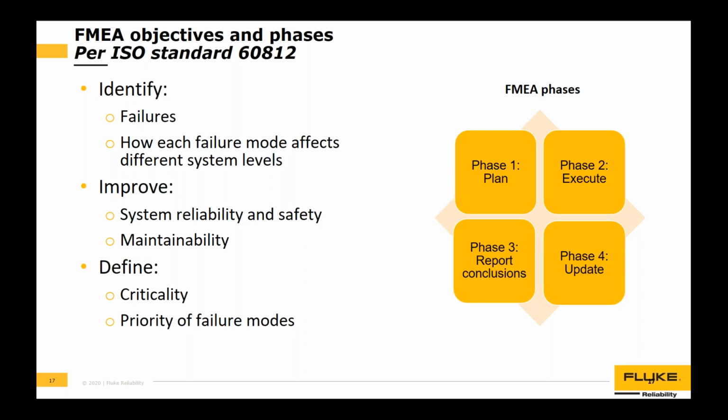Because if you think about it, in a traditional safety or environmental world, when they talk about risk, it's the frequency of occurrence times the severity of the occurrence. But in reliability, we throw one other caveat to it, because if I can identify it, I'm not going to let it happen. And that's where we actually provide value to the organization. It's that next level of risk assessment and understanding. And then for those that have a very high risk, we figure out what the right thing to do is to put in place to prevent it, predict it, mitigate it, whatever the right situation is.